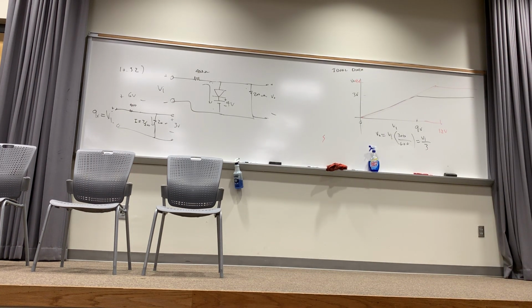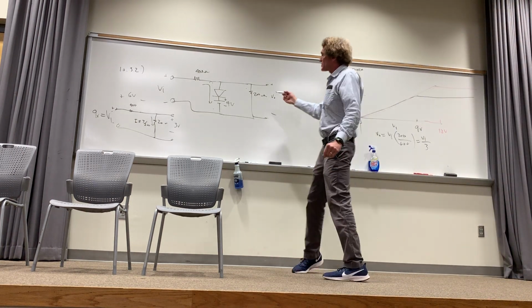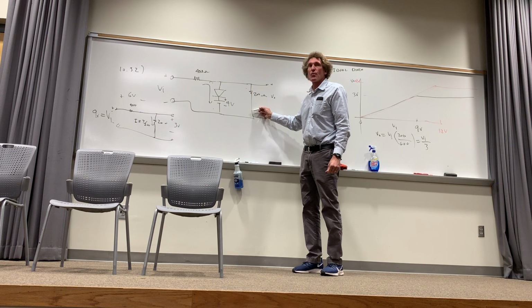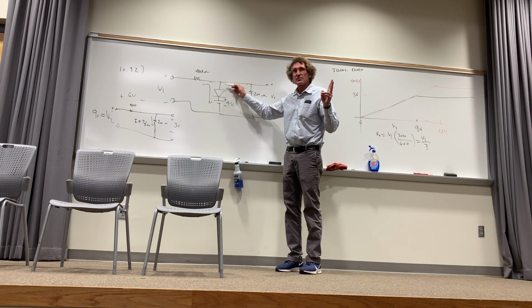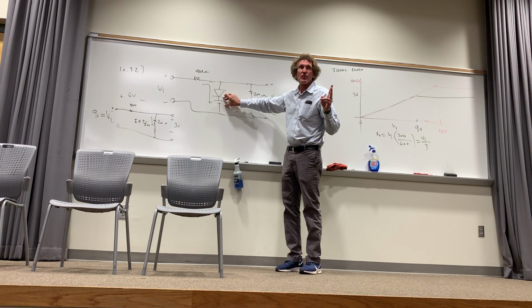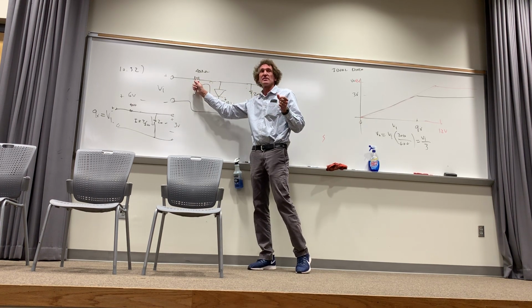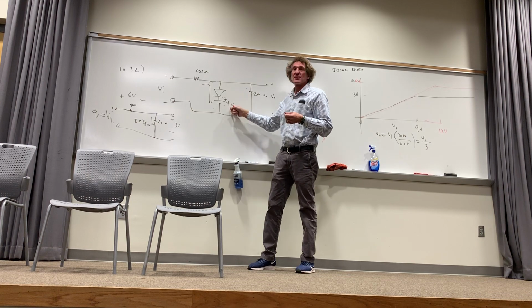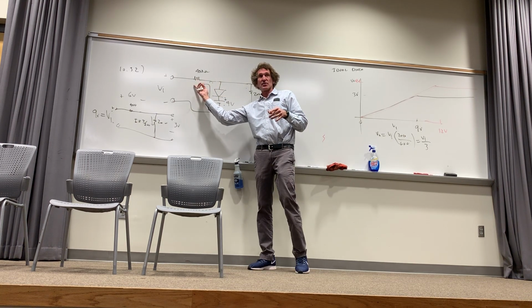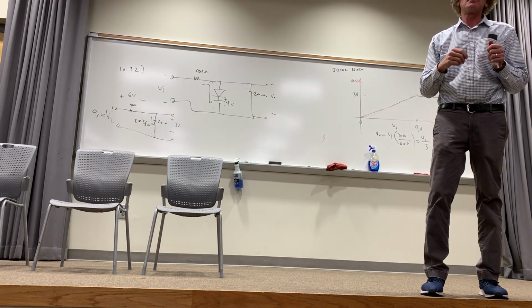Can you explain again why it stays constant out there? All right. Suppose, just for a thought experiment, that I wanted to put 4.1 volts here. Just think about this. Well, 4.1 volts would cause this diode to turn on. That diode's a short, so it will drive it down to 4 volts. And the reason it can't be higher is because the current that's causing that 4 volts is being supplied through that resistance. All the voltage drop will be limited to 4 volts there, the rest here. So you get more current as you increment the voltage. The current increases, but the voltage output doesn't.